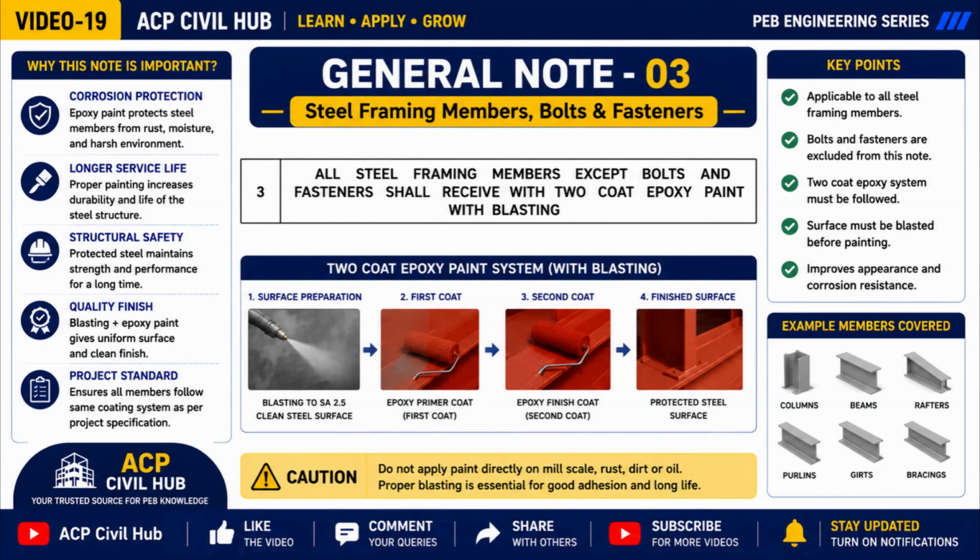A clean surface allows the paint to bond properly with the steel. After blasting, the first coat of epoxy primer is applied to provide corrosion protection and strong adhesion to the steel surface. Once the primer has cured, the second epoxy coat is applied to improve durability, weather resistance, and long-term protection against moisture and corrosion.